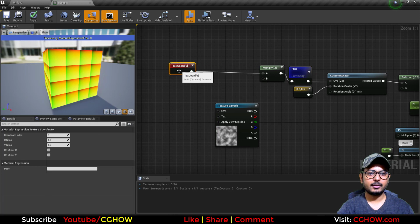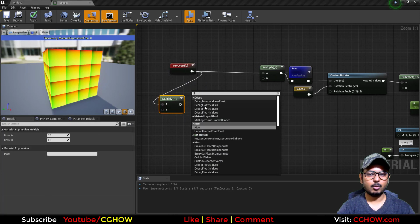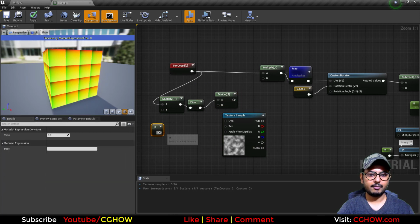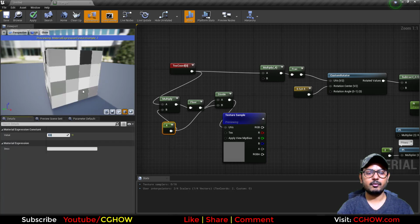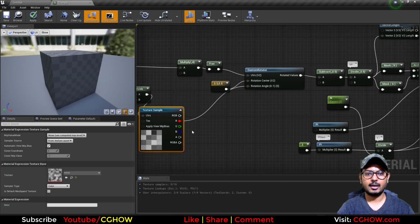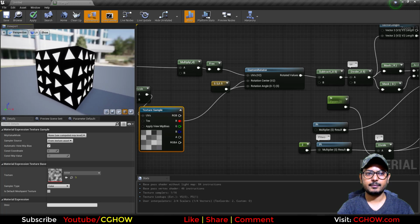To do that, you can multiply your UV, then take a floor and then divide it by the same value you have in your multiply, and connect it to your texture. And if I put 4, it will give you 4x4 random noise. And now you can use this in your rotation, and you can see every triangle is rotated differently.